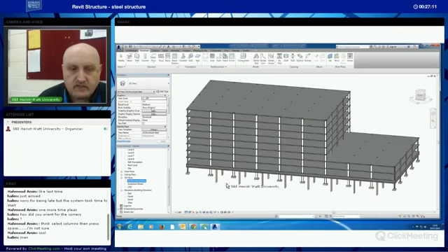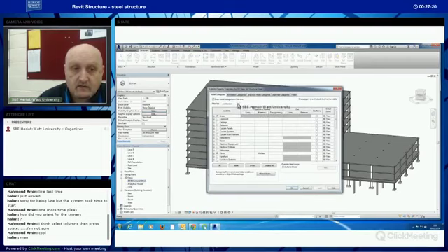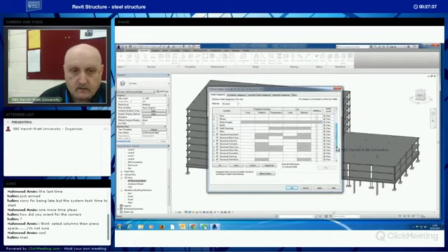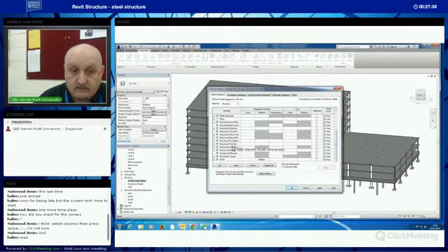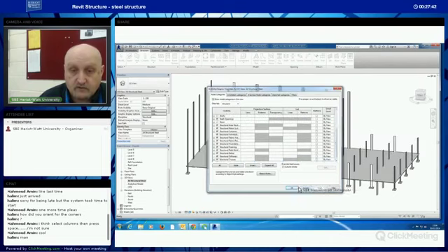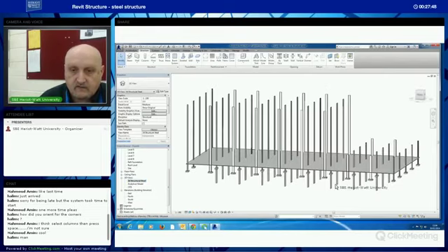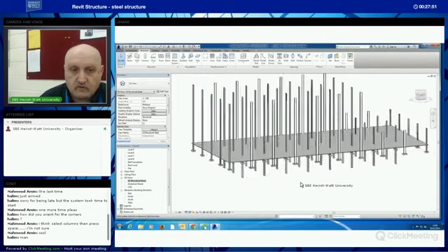And then I'm going to change what this is displaying. So making sure that this is bold and I'm actually on 3D Structural Steel. I go into Visibility and Graphics here, and I'm going to simply show structural elements. I don't want architectural elements shown. These are all unchecked, that's fine. In fact, even within structure I've got too much going on here. I don't want to be showing the floors or generic models or lines. I don't want walls shown either. Just leave it at that. Nothing else showing. So the floors will disappear. I'll keep the foundations in. Handy to see them. Kind of a good visual guide of what's going on.